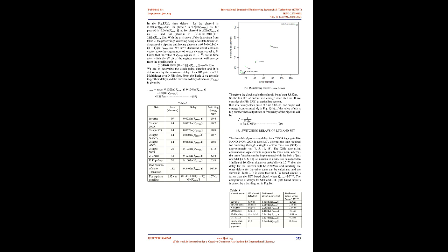When a charge tunnels through the tunnel junction, the amount of total energy in the circuit changes before and after the tunneling. So the difference between the energies before and after the tunneling event is calculated by the relation in equation 18. And it is the amount of switching energy consumed when a tunnel event occurs in the tunneling circuit.